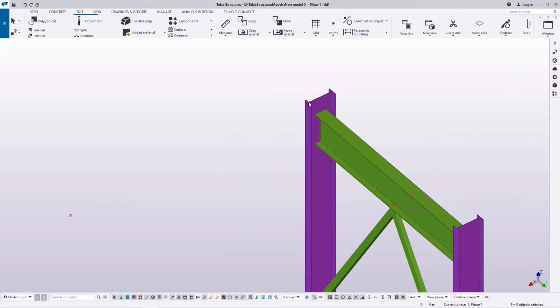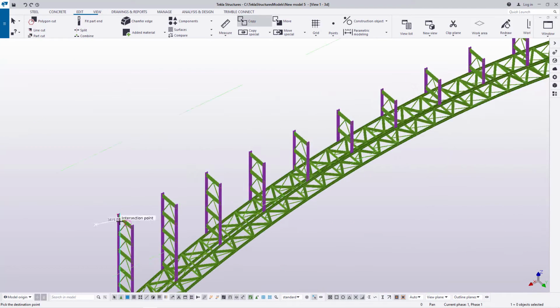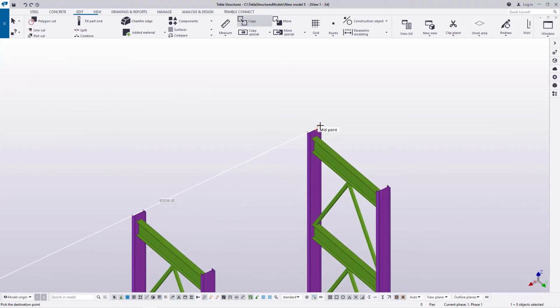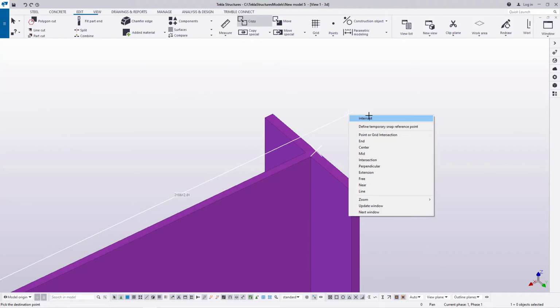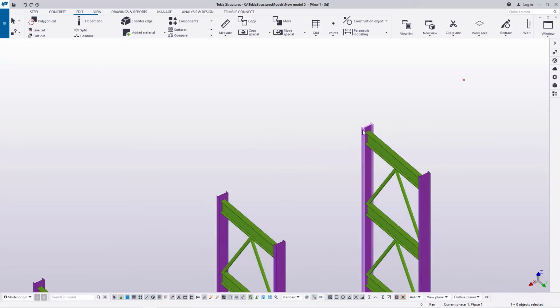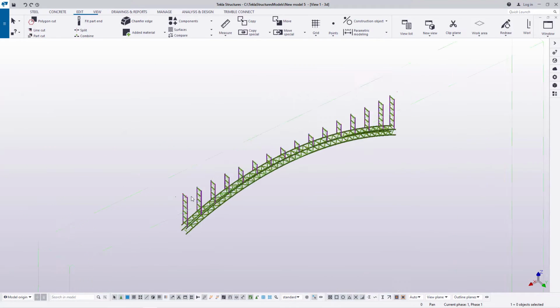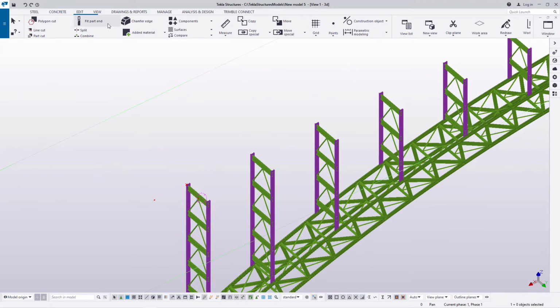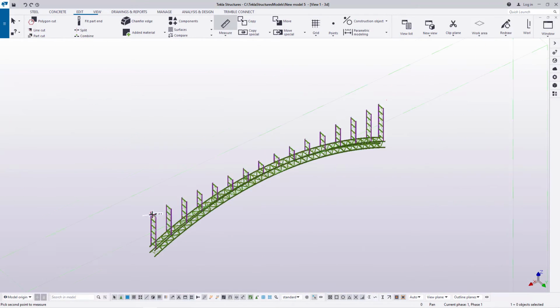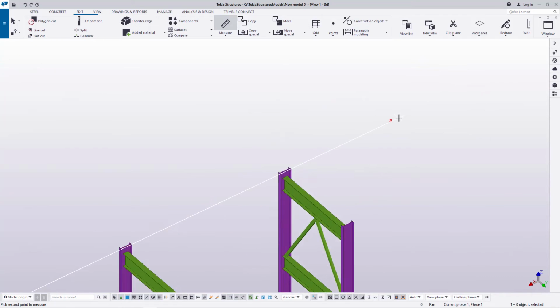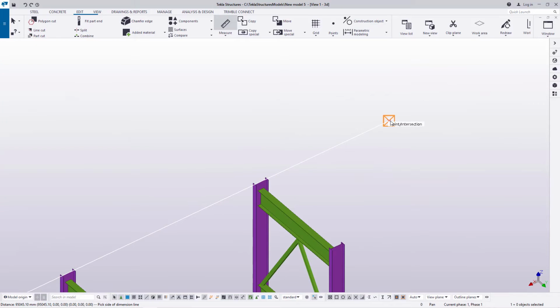So I'll select this point, right click and come to copy, and pick it from that position and go all the way to this far end, and I'll place it right here. Once I've done that, I have these 2 points stretching all the way. You can even take a measurement. You come to measure, and you want to measure this length. This is 95 meters.